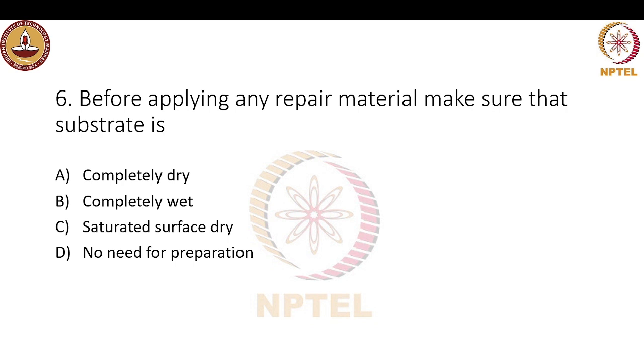Okay. So next question is, before applying any repair material, we have to make sure that the substrate is completely dry, completely wet, or it should be saturated, or the substrate need not have any preparation. It should be saturated, surface dry. Yes, ma'am. Option C.